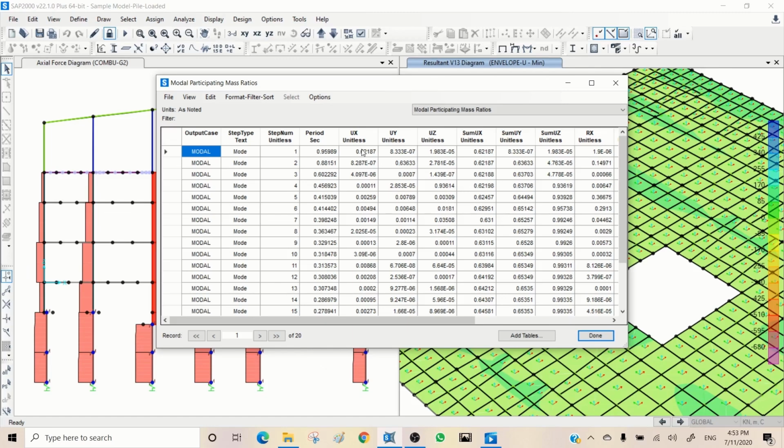It's not necessarily the first and second one. It could be number 4 and number 10. It really goes back to the period you have. Sometimes you have some very soft elements in terms of stiffness. So you may have, for example, a cantilever here with a period of more than 1 second. And this cantilever is nothing. The modal participating mass ratio could be less than 1%, even 1.1%. But it's there because this is the highest mode. The order you see here is based on the highest period, but it's not necessarily the fundamental period.